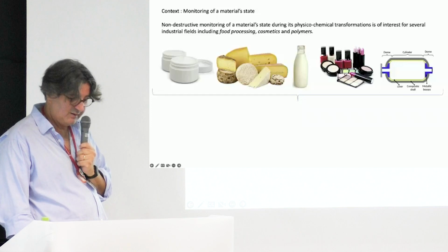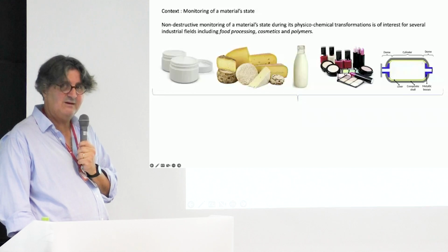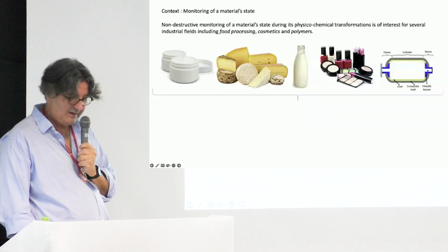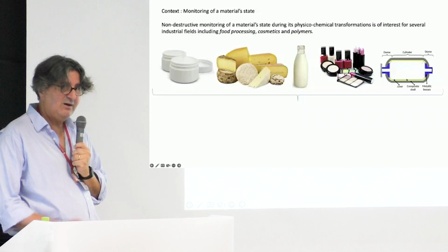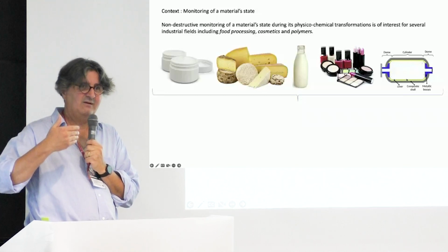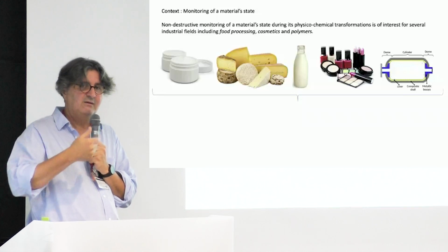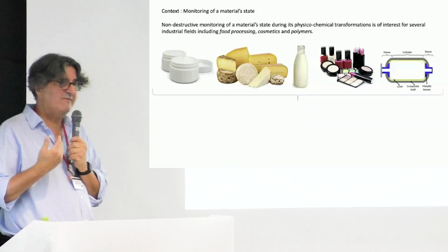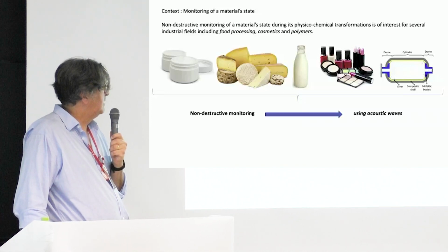And for instance, there is one point that is very important. In these tanks, you have a metallic part that is in contact with the liner, because hydrogen will be taken out and in through this metallic part. And if you have a degradation of the bonding between the metallic part and the liner, then you may have a leak of hydrogen, which is not desirable.